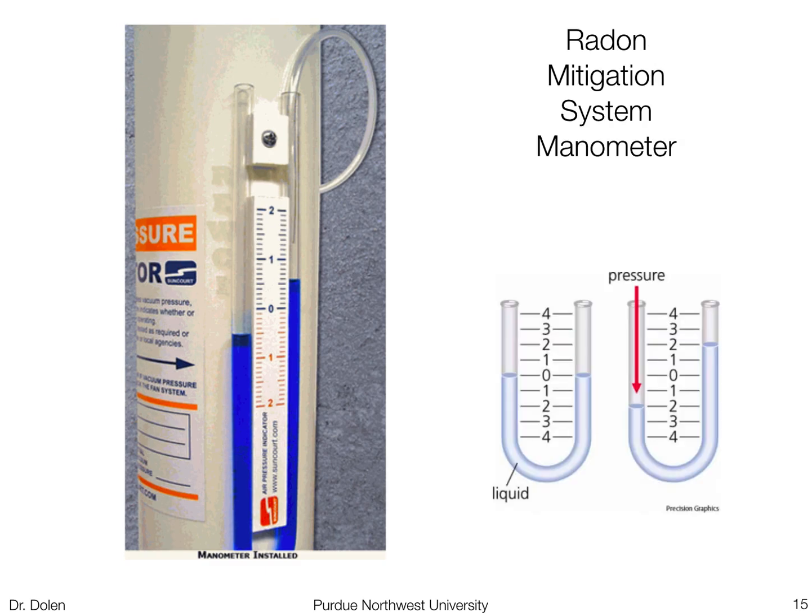This is a particular type of manometer, and a manometer works pretty simply. You have a tube that's U-shaped. If you have the same pressure in this opening and this opening, you should expect that water level to be relatively constant. But if at one opening you have a different pressure than the other opening, there's going to be a bigger force applied on this surface of the water. So the water won't be level on either side of the manometer. And based on that difference, say it's 2 inches high or something like that, you can actually measure the pressure on the other side of the manometer.